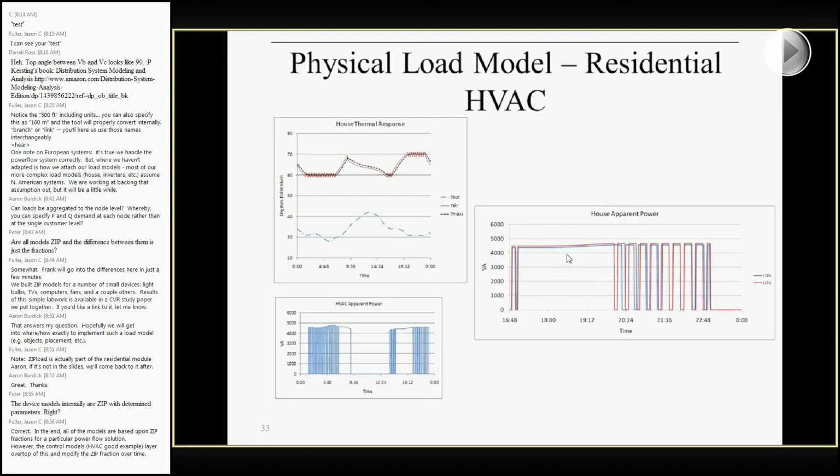This is really nice, especially for doing different types of mitigation strategies, demand response, things of that nature. The fact that the physical multi-state model is still behaving how an actual system would, but it's factoring in all the system-level effects that you're trying to influence and see what kind of benefits you can get. So it's nice that it captures that level of detail, especially for the distribution system analysis where, you know, you may want to reduce the voltage by 2 volts, but what does that actually get you? It's not just a straight one-for-one trade of, okay, I got 2 volts reduction, so the power must go down by that.